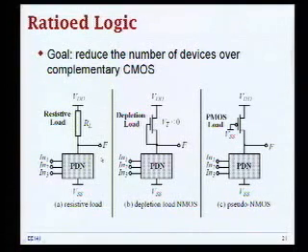And this resistive load really mimics the pull-up resistance of your pull-up network. It has some value, okay? And what this gives you is obviously reduced implementation area, which was the main goal. But it also adds some negative effects.